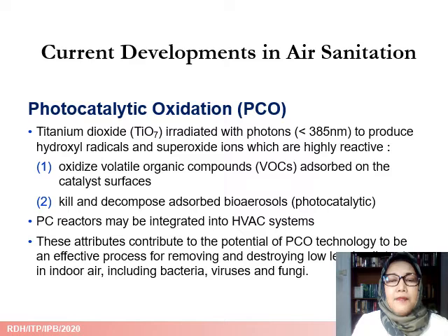Now here is some technology under development for air sanitation. Photocatalytic oxidation using titanium dioxide irradiated with photon to produce hydroxyl radical and superoxide ions, which are highly reactive to oxidize volatile organic compound or VOCs adsorbed on the catalyst surfaces and kill and decompose adsorbed bioaerosols.